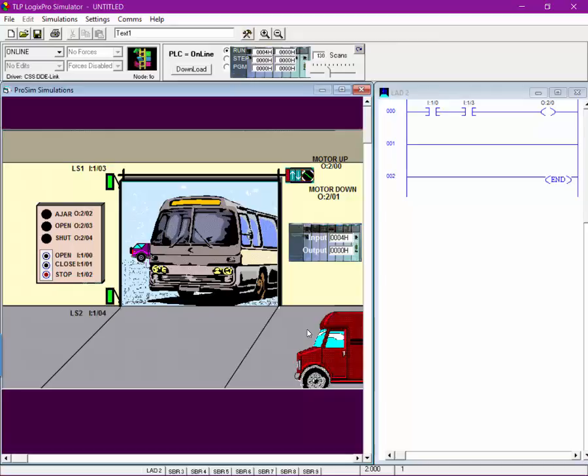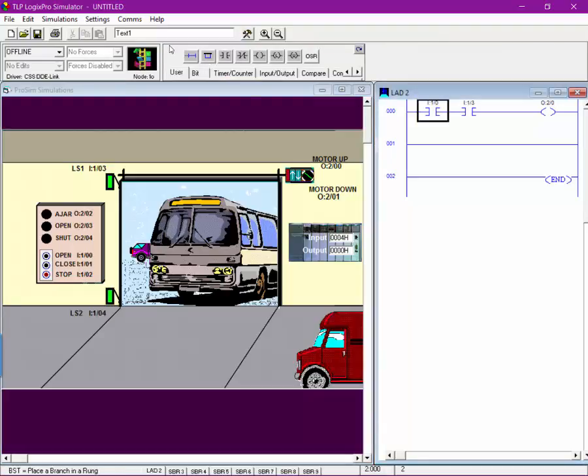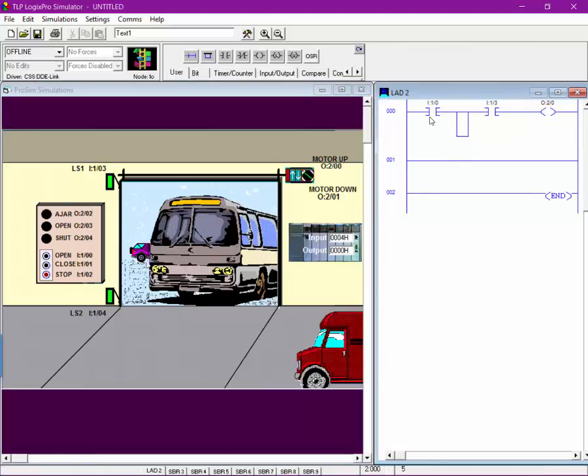Normally you would sit down and flow chart this and figure out how you want to do it, but I'm doing it step by step to get across what each of these buttons does as I go through. So let's go back here and put in, and I'm just going to show the rung here that keeps it from going. I move that to here, and then I select this one and put in another switch, move it down to here, and call it the same name as the motor.